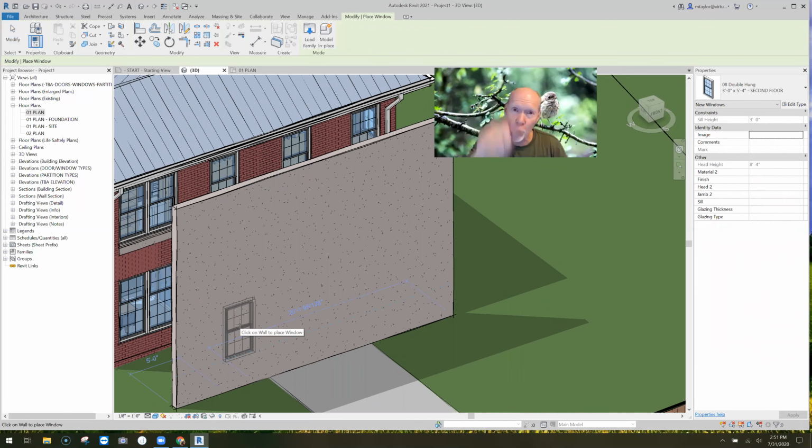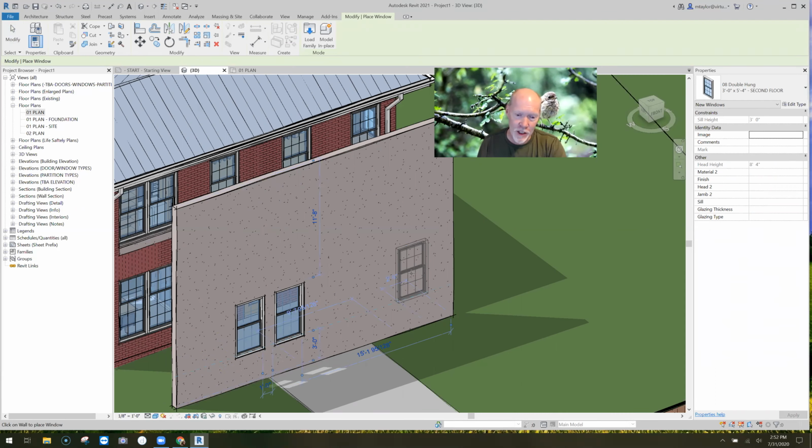And you guys know about putting windows when you're in 3D, that each of the windows has a default sill height built into them. You can set that when you make the window. But take a look, when I place this thing, I get a horizontal inference line and it actually snaps to it when I'm hitting this particular window's sill height. Every window's different. You can set them differently. And it goes for the second floor as well. So you can do this, boom, just like that.